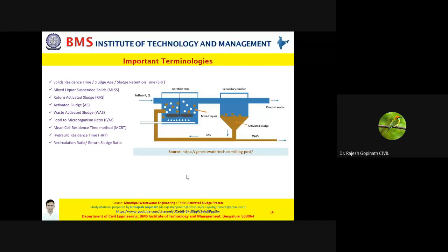Now what is MLSS, mixed liquor suspended solids? Now this entire system you see here: when the settled sludge, that is activated sludge, is returned back here, and is mixed with your wastewater and along with your microorganisms, this entire mixture is called mixed liquor. It's called mixed liquor suspended solids. So please do not forget this terminology of MLSS.